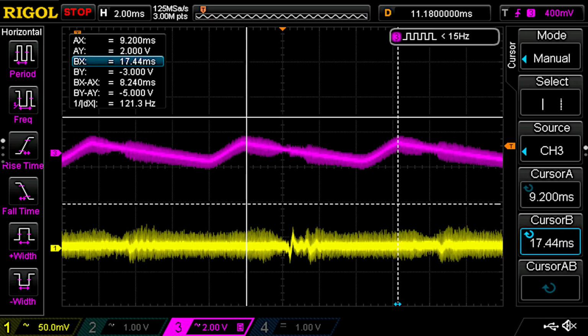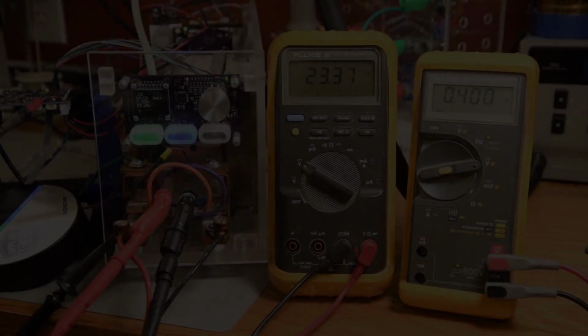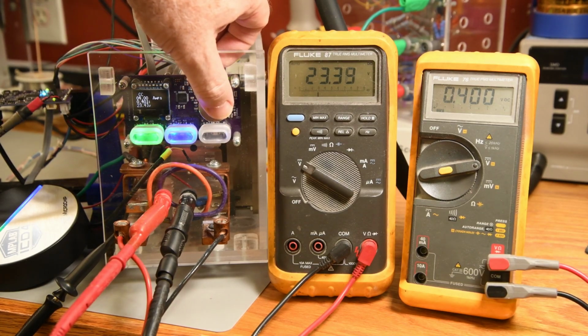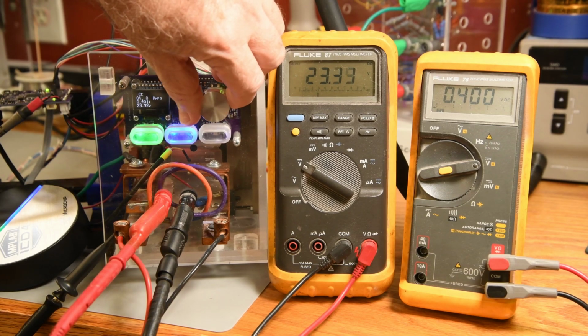Again, I don't know if they are really there or if it's just being picked up in the ground noise by the scope probes. I think the safest thing to do is to assume the noise spikes are really there. I'm planning on doing a bit better with filtering on the next power supply. We'll see what it looks like then.